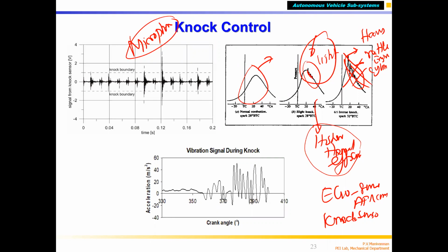So if you try to get more torque because the vehicle is not moving, what is the natural tendency? Press the accelerator. You get more torque by injecting more fuel, so you press the accelerator pedal. You think that you are injecting more fuel and the engine will accelerate. No. In that condition the engine speed is already low, and the air-fuel ratio and all these things are not in proper condition. It doesn't give proper combustion, so the engine is not producing torque.